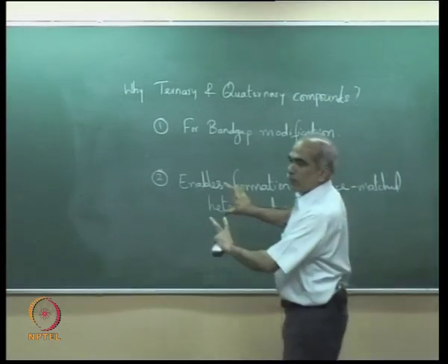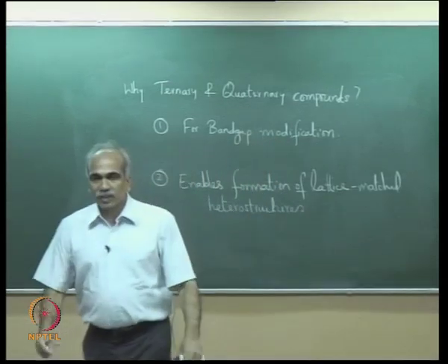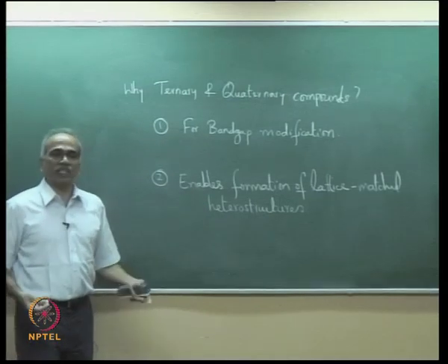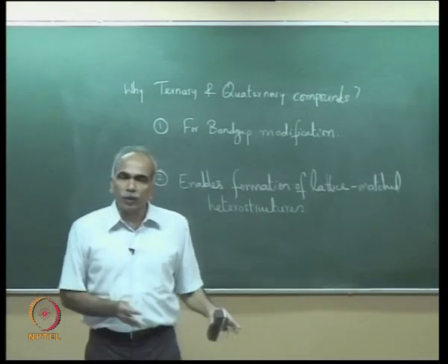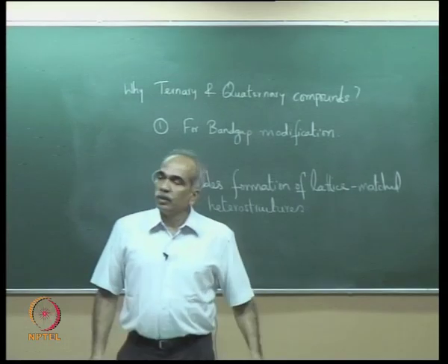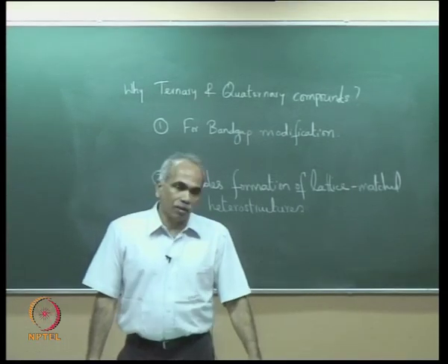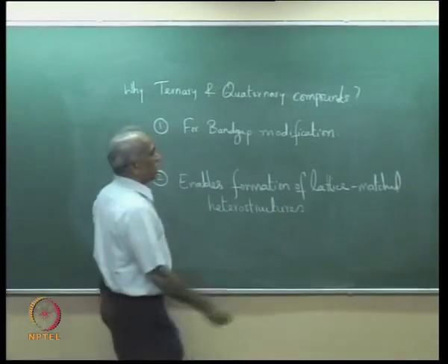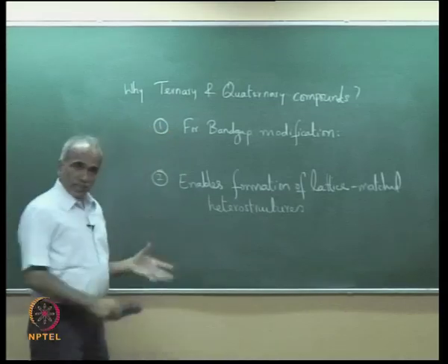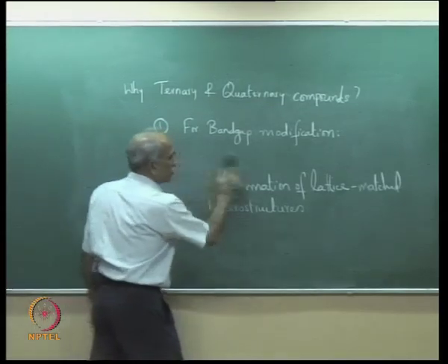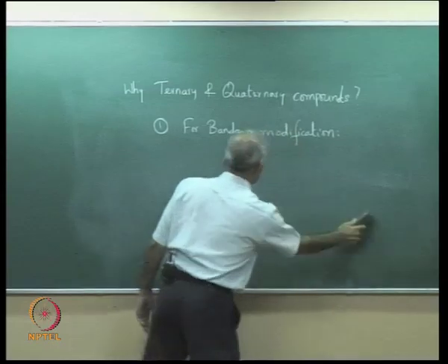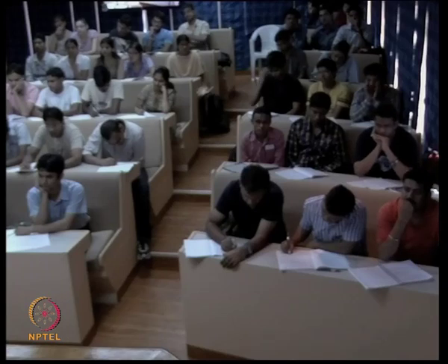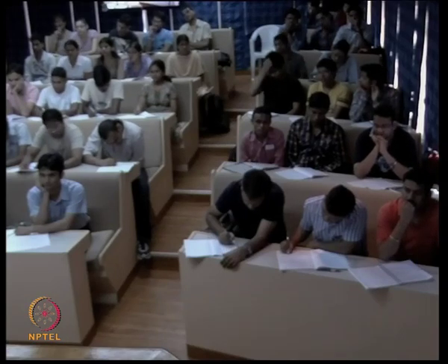We will discuss the second point in the next class. Heterostructures, growth of heterostructures, design considerations, and lattice matching issue. Lattice matching means basically the lattice constants of the compounds which are used to form heterostructures have to be the same, lattice matched. So we will discuss this later. First, let us see band gap modification. As I mentioned, by changing the composition, so let me rub this point, we will discuss that in detail. So for band gap modification, let's take an example and discuss what this is.